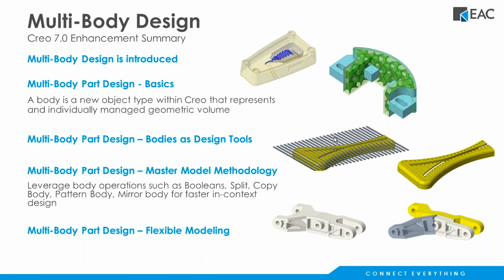One of the things with these bodies is we can categorize them as a construction body. So it won't be listed in a bill of material. It won't be listed in mass properties or anything like that. Sort of like a skeleton part in a way. It's used to help build something else. So that's what was done in this particular example.